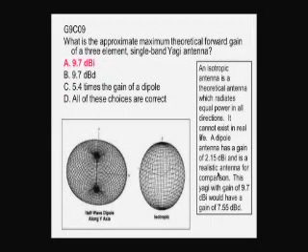But a dipole antenna has a gain of 2.15 dBi, and it's a realistic antenna for comparison. So this Yagi with a gain of 9.7 dBi would actually have about 7.55 dBd, because you would subtract the difference here with the dipole. The D here is comparing it to a dipole antenna now instead of the phony isotropic thing.